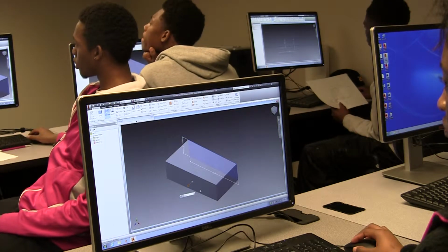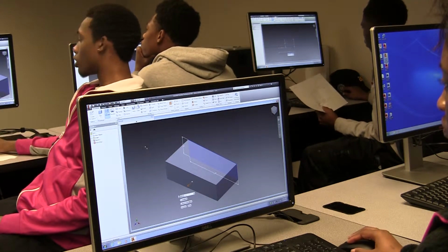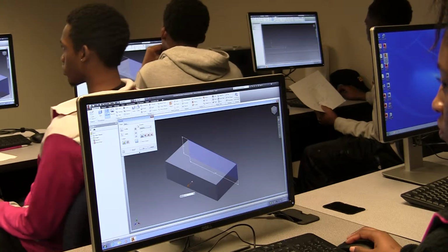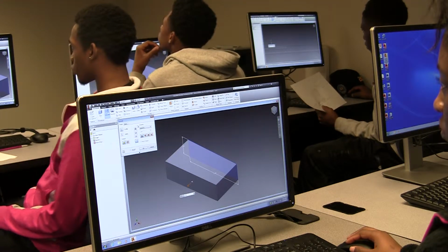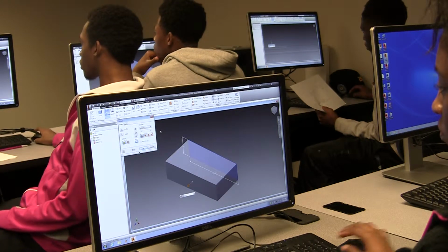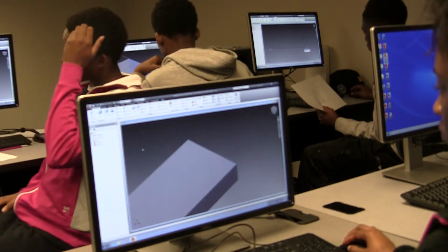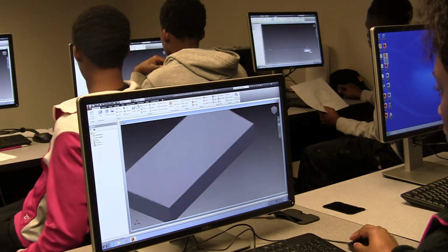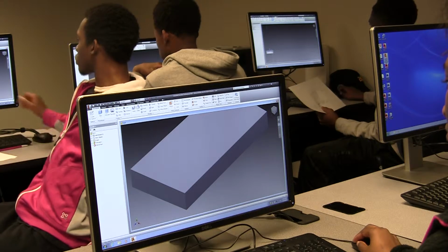From there, if you have your extrude properties, you can tell the computer how wide or how narrow or how thick or how thin you want your object to be. So right now, we're gonna extrude it out to about 4 inches. So you should see the number 1. You'll change the number 1 to the number 4 and then press OK. You'll see that your rectangle has now changed size. It's a solid block. Does everybody have it before I move forward?